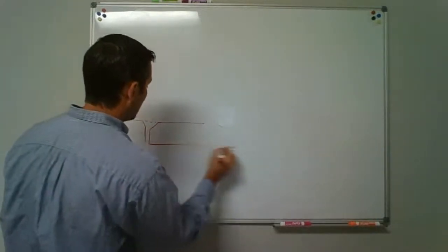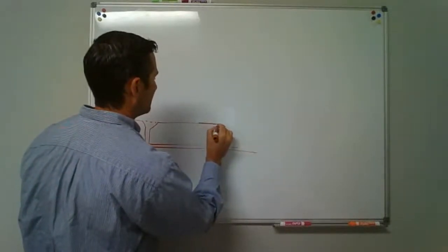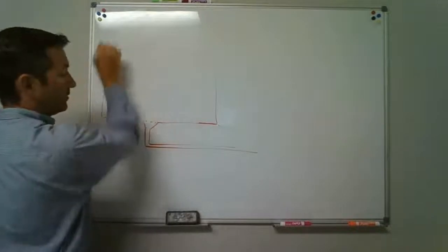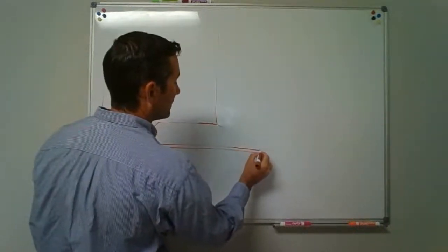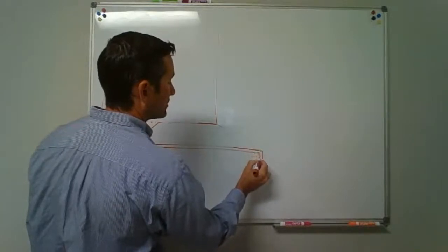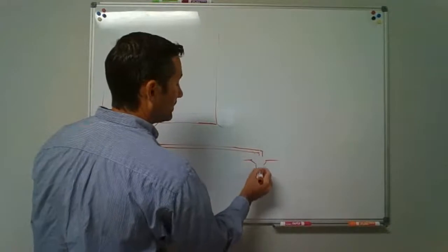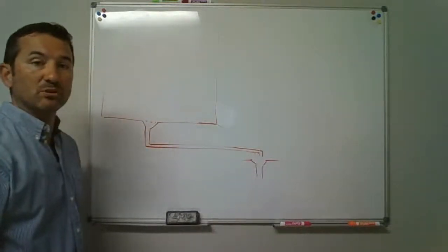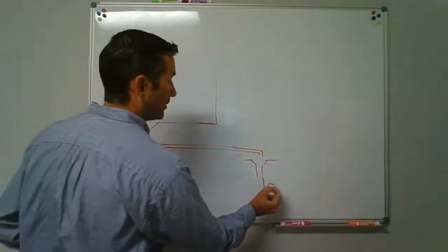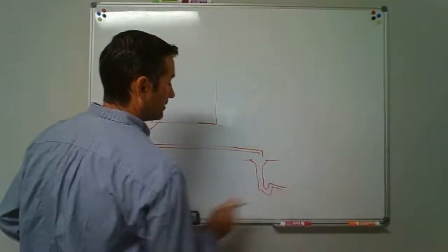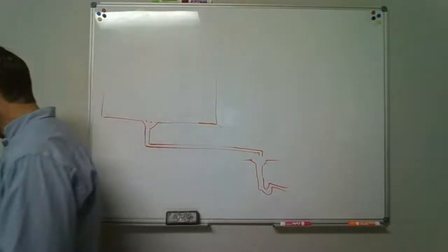So it says we'll take that out as an indirect waste connection. Here's our big walk-in place where all our food storage was. It takes it to the outside somewhere, and then that discharges indirectly into a waste receptor. Okay, that's what you're going to have. Now that one will be trapped on that.